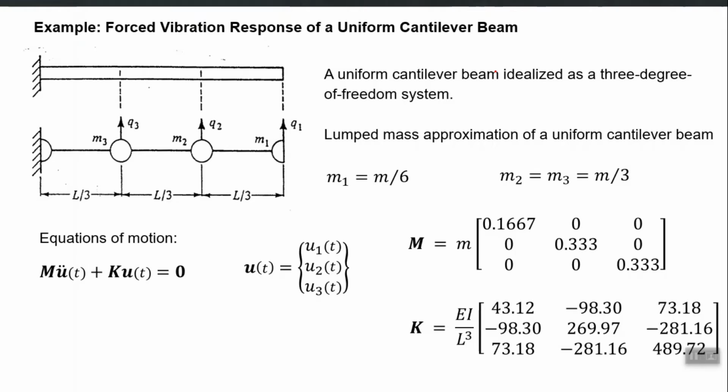So this simplifies our solution of equation of motion greatly. All we need to do is to just first calculate the capital phi matrix. That is the main matrix which is used in this modal RHA. That matrix helps us in transforming our governing equation of motion. That matrix also helps us in bringing the solution back to the original physical coordinates. So this method is called modal RHA or modal time history analysis. So it is the forced vibration analysis now.